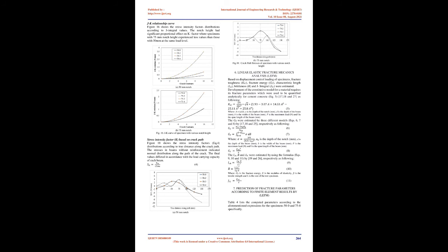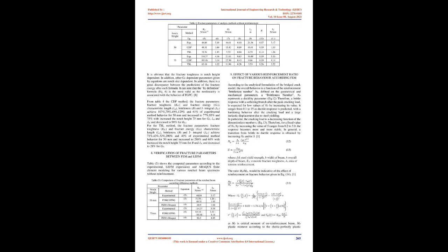Fig 14a shows the failure load for 50 and 75 mm notch height with various reinforcement ratios. The bar chart reflects that the finite element methods give results closer to the laboratory results by a deviation of 15% in the case of failure loads for all reinforced rebar. According to using two methods in FE analysis, Figure 15 gives the relationship between the two methods, based on the same characteristics of the model specimen.